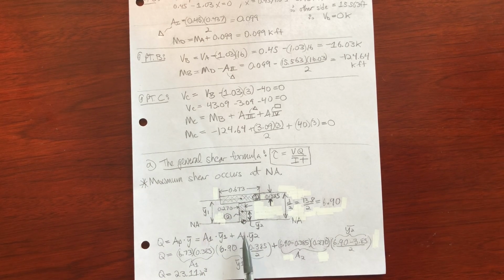Okay, we're going to add A2. A2 is the width there, which is the flange width, which is the web width, which was 0.270, and then the height here we know that this whole height was 0.690, right? This height minus the thickness of that flange gives us that. Together we get A2. And now Y2 is a dimension from the centroid of area 2 to the centroidal axis,